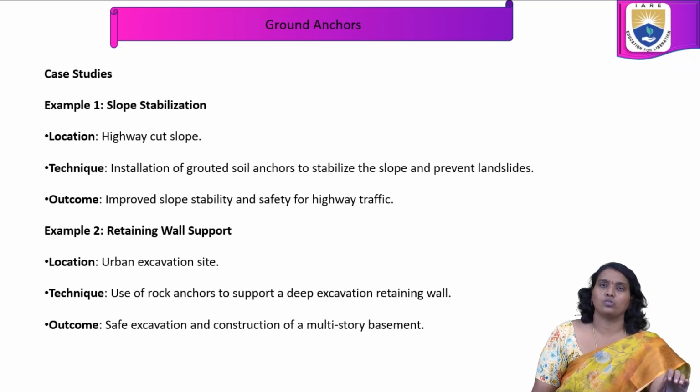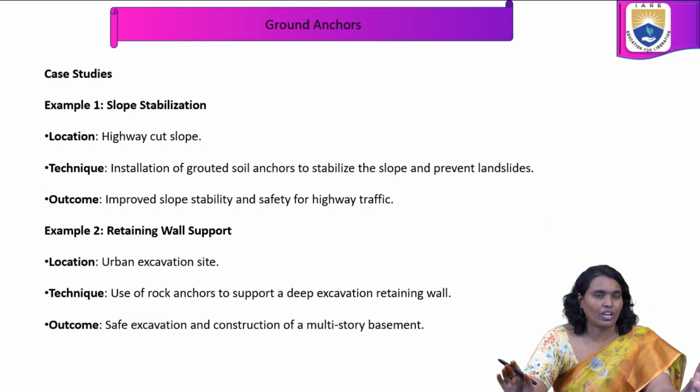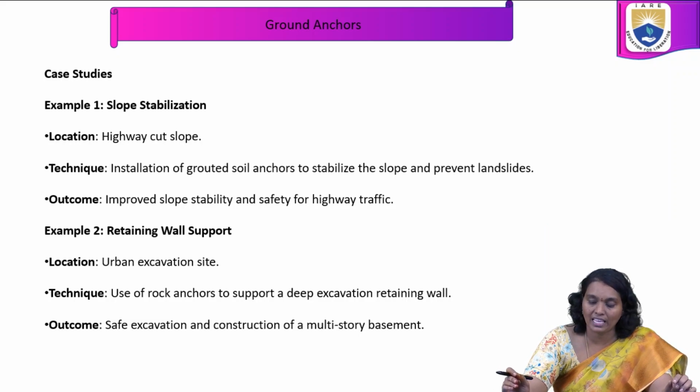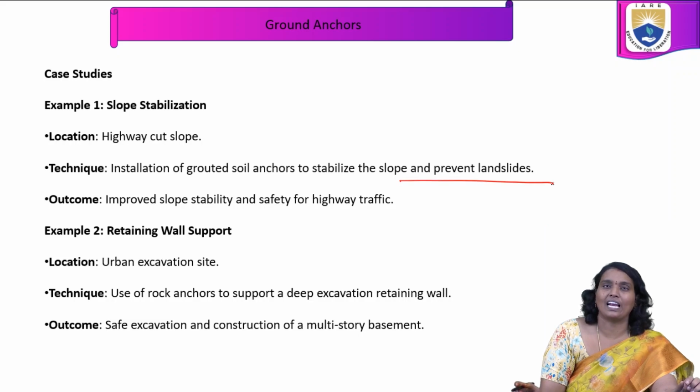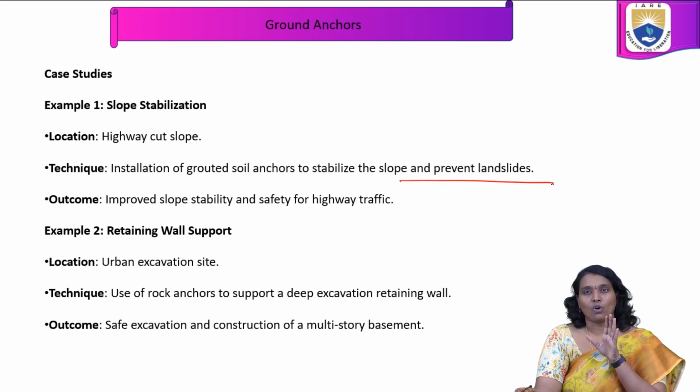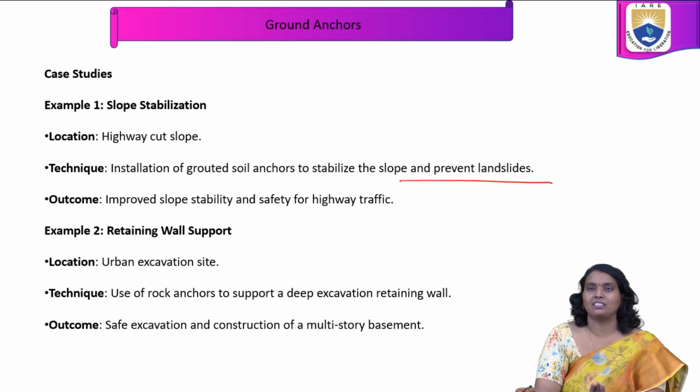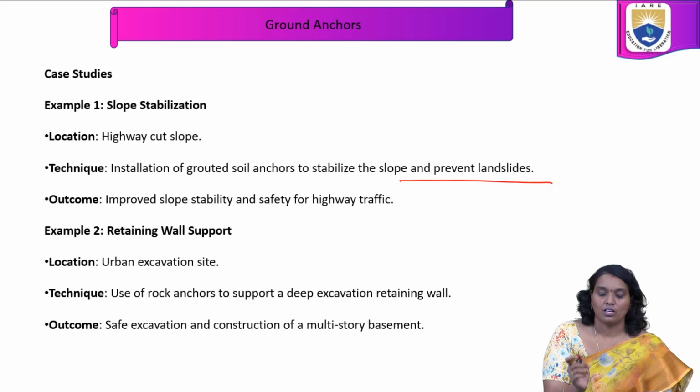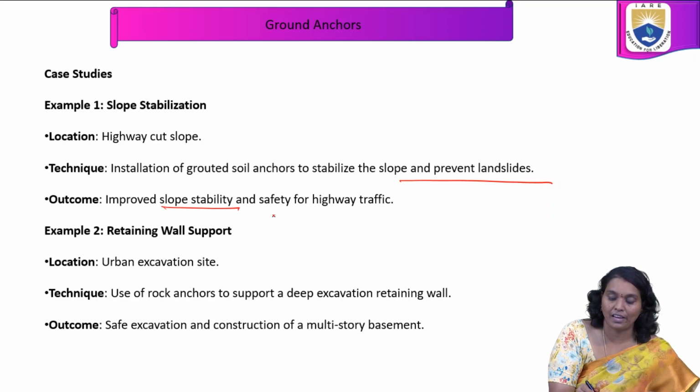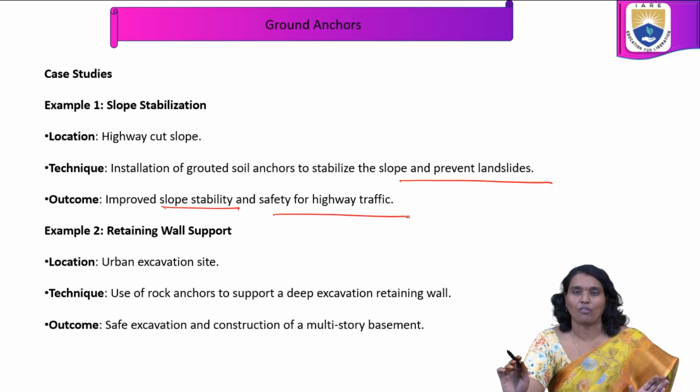In this also, slope stabilization at the location of a highway cut slope. So in this technique, installation of grouted soil anchors to stabilize the soil and prevent landslides. We choose the soil anchors to stabilize and prevent the landslides. Because of using this technique at that particular highway cut slope, it improved the slope stability and also safety for highway traffic.